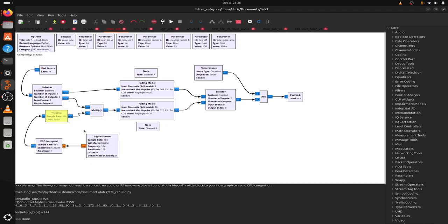This is for part 2. This is actually pretty similar to what you had asked for in that initial part 2 before the update. And so I did use ChatGPT to help clarify, I think, what was being asked. So hopefully I got it right. So anyways, what I was after here was that 0.1 hertz frequency, which is the slew rate of that frequency offset, and then an amplitude is going to be the maximum offset, and that's just passed in as a parameter here that will change on the top block side. So that's being passed into a voltage controlled oscillator of the same sample rate as everything else here, a sensitivity of 2 pi and an amplitude of 1.